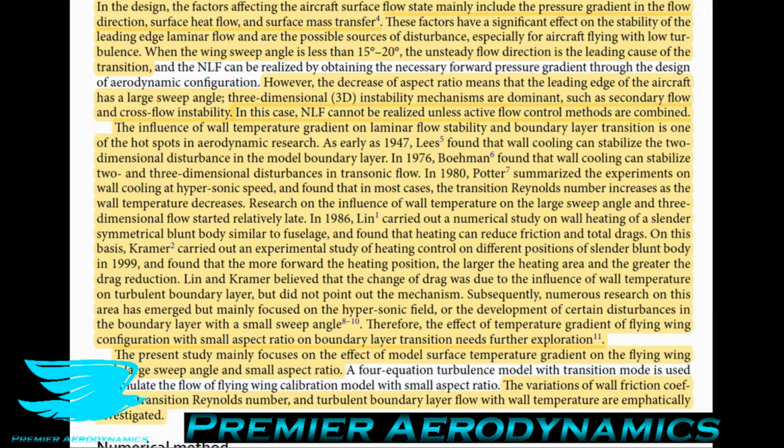The induced drag is very well known in terms of its visual representation, which is the vortices that it produces at the wing tips. If you go to Google or DuckDuckGo or whatever, and you type in just wingtip vortex, you'll see a bunch of really cool pictures showing this. And what happens is the high pressure on one surface of the wing bleeds over to the low pressure on the other side, and this creates a vortex. This is the visualization of induced drag, and induced drag is what it sounds like. It's drag. It's a loss.